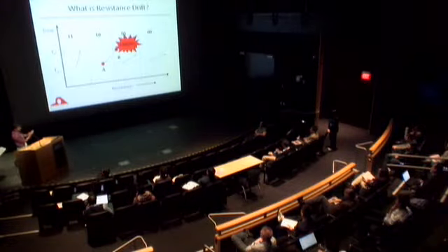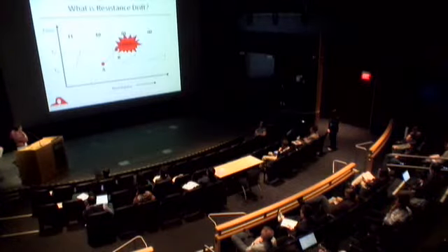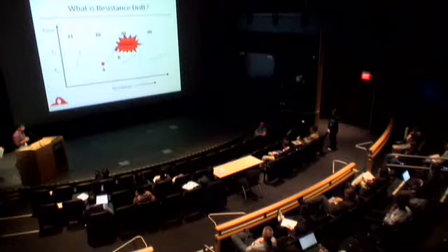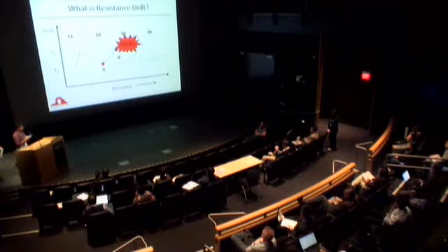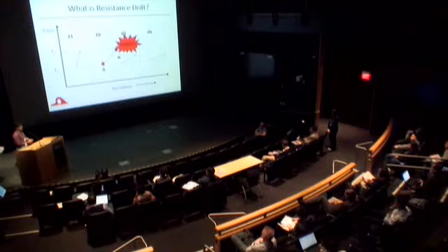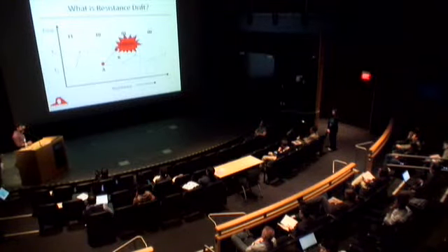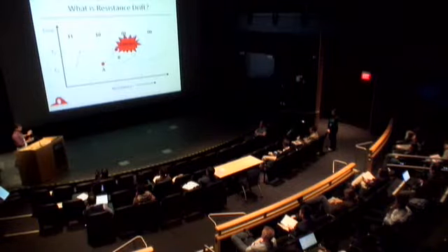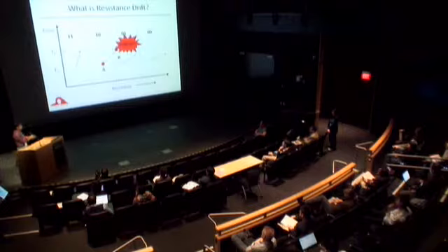Just to state as a fact, the rate of drift increases as you move towards a higher percentage of amorphous. Is it the same for the different cells? Is the rate of drifting the same for the different cells? That also depends on a number of factors. There could be process variations that could come into place. But for one given cell, if you look at the cell in isolation, the rate of drift for a particular state increases as you increase the percentage of amorphous content.